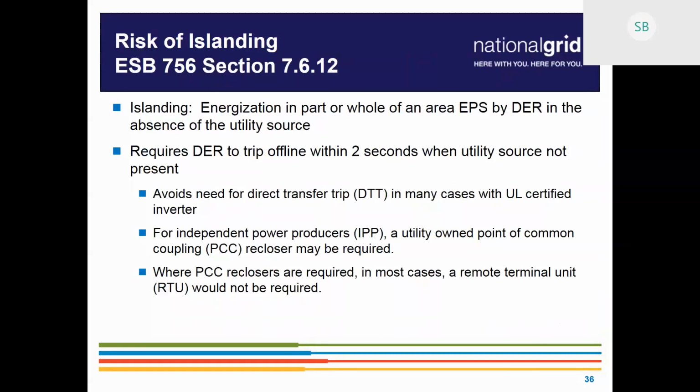generator. But what that means too is that we have our sensing and our monitoring and control of the device at the point of common coupling. So that's why it makes the most sense for independent power producers, because if we need to turn the site off, whether you turn it off at the PCC recloser or at a specific generator breaker, it's kind of the same from our perspective, and it's the same from your perspective. If you have a behind the meter scenario and we do this at the point of common coupling, we're going to take the load down as well as the generation. So that's why it's a little case specific.